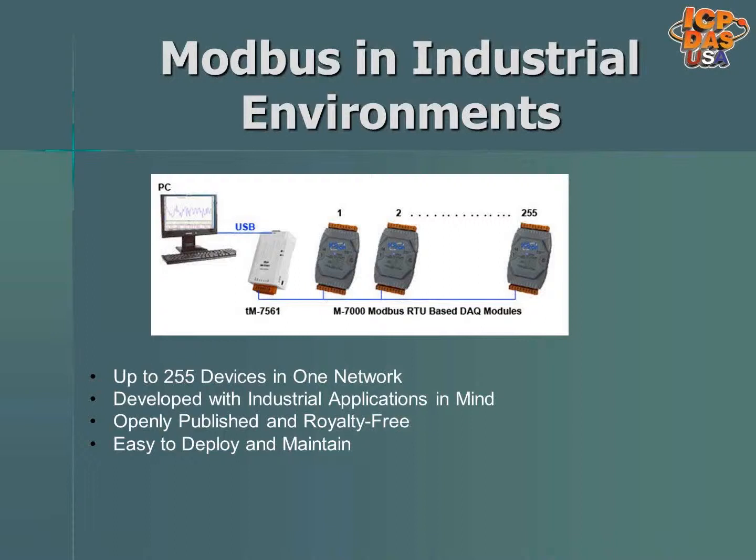Modbus applications are easy to deploy and maintain. Each Modbus device in a network is given a unique address. In serial Modbus RTU networks, only the node assigned as the master may initiate commands. In Ethernet-based Modbus TCP networks, any device can send out a Modbus command. One master device is usually configured to send Modbus commands. A Modbus command contains the unique Modbus address of the destination device. Only the destination device will act on the command, even though other devices might receive it.